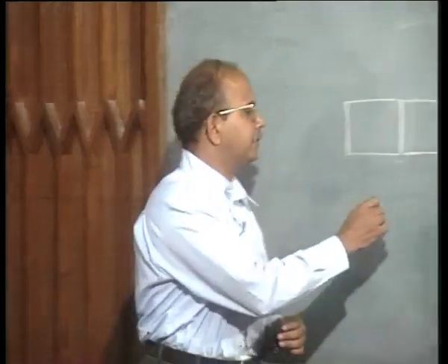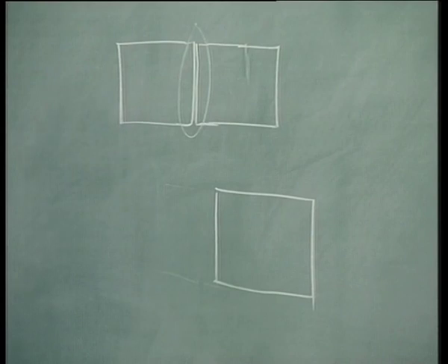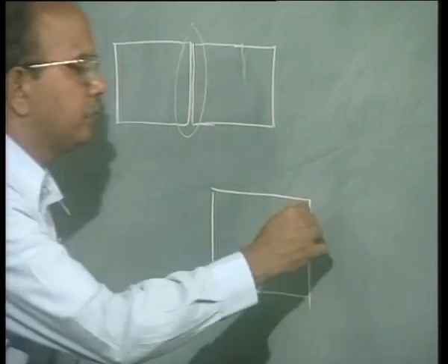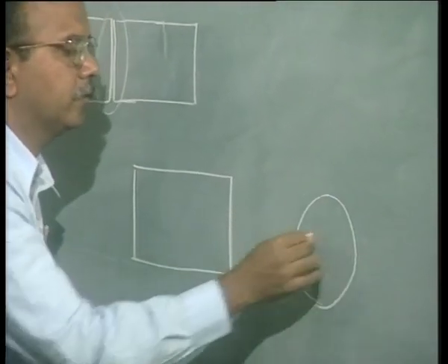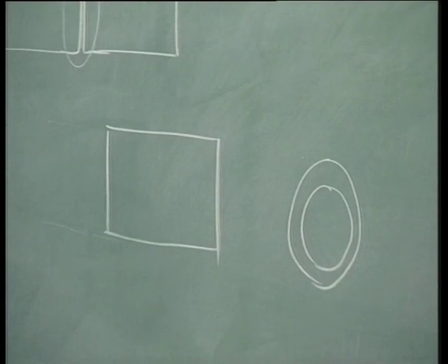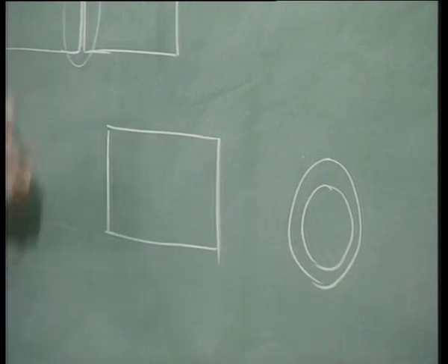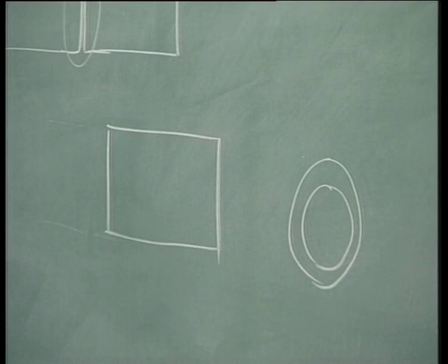All of you said that we can take symmetry, fine, okay. Actually this is a pipe, so this view looks like this, okay. There is a pipe like this. We said that we will use a shell element throughout, a 4-noded shell element to model this, okay. That is all fine, and also the thermal boundary conditions were very clear, right.